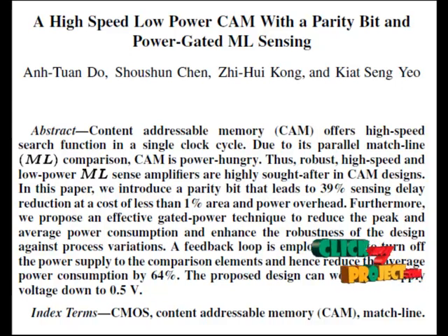To achieve effective data searching, the data comparison architecture of CAM is usually implemented in a parallel operation structure. However, due to this parallel characteristic, power consumption is always an important concern when designing CAM circuitry. That is, content addressable memories simultaneously compare an input word to all the contents of the memory and return the addresses of matching locations in a single clock cycle.